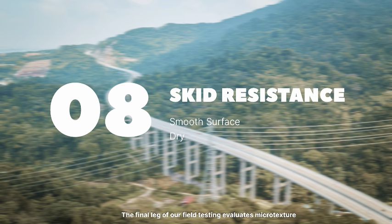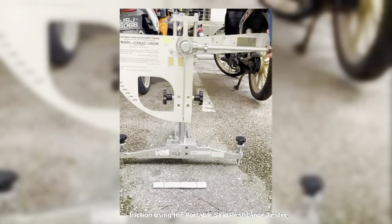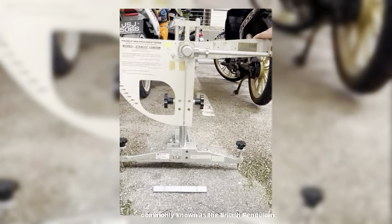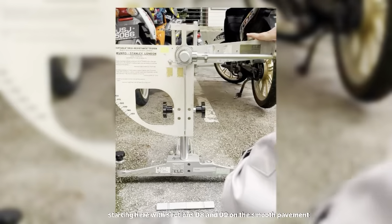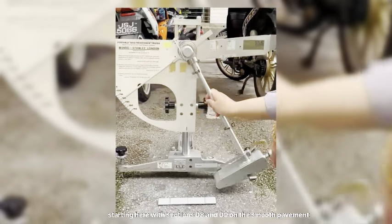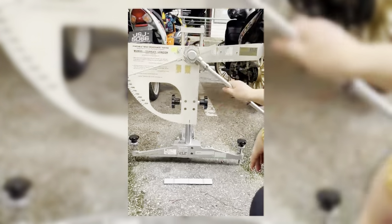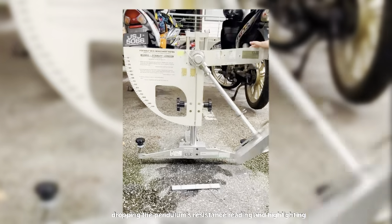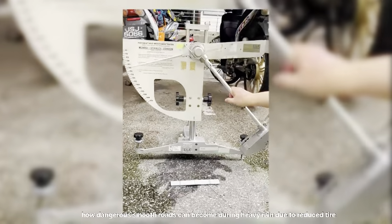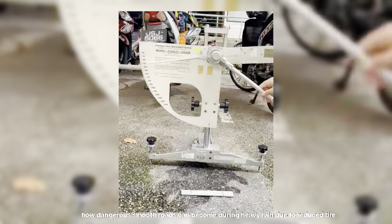The final leg of our field testing evaluates macro texture friction using the portable skid resistance tester, commonly known as the British pendulum. We conducted this sweep across 4 distinct scenarios, starting here with sections 8 and 9 of the smooth pavement under dry and wet states. The presence of water dramatically changed the friction value, dropping the pendulum resistance reading and highlighting how dangerous smooth road can be during heavy rain due to reduced tire to pavement friction.